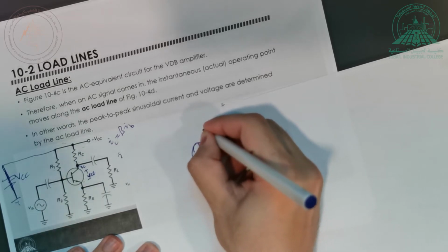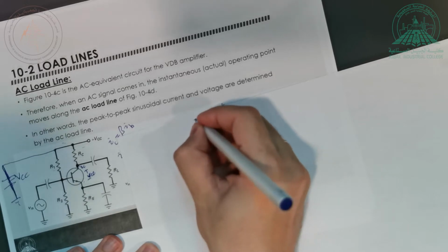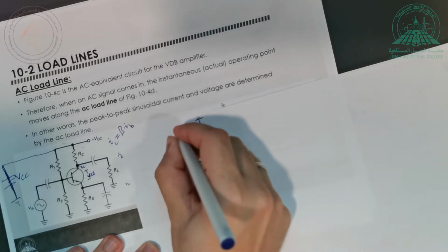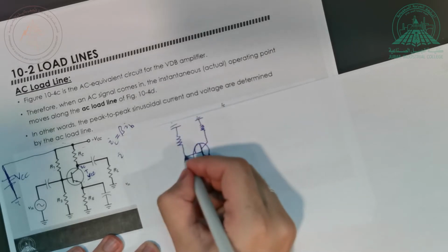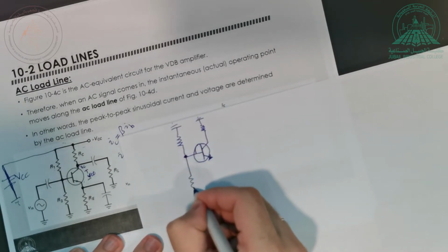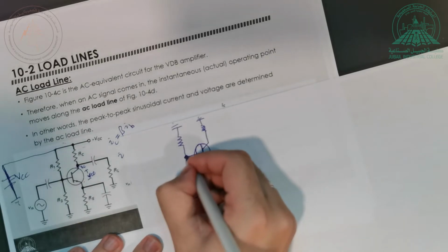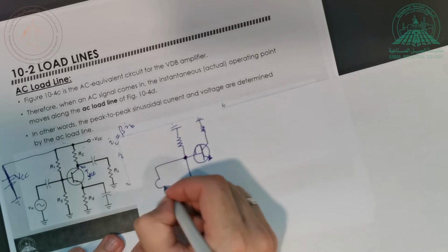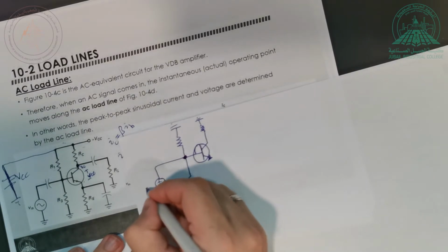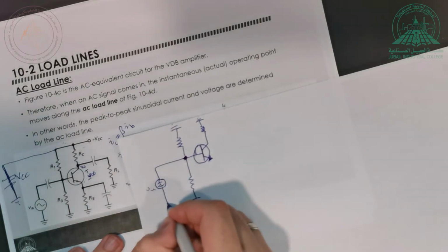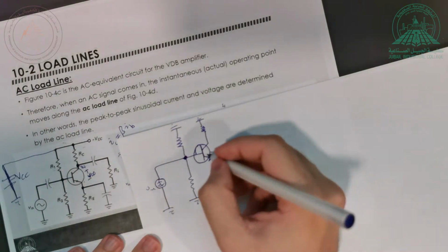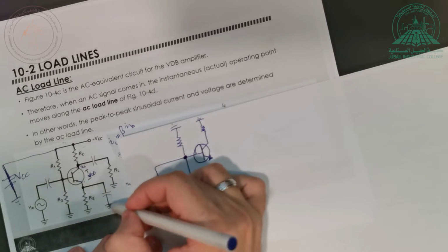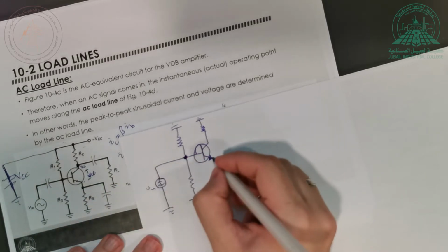This is RC, and RC is going to be connected to the ground. Here I have R1 also connected to the ground. Here I have R2 also connected to the ground, and from the left the capacitor will be short circuit. So here I have my VN to the ground, and then if I look here, this will be short circuit, so it will short out RE. So RE is not going to appear anymore.